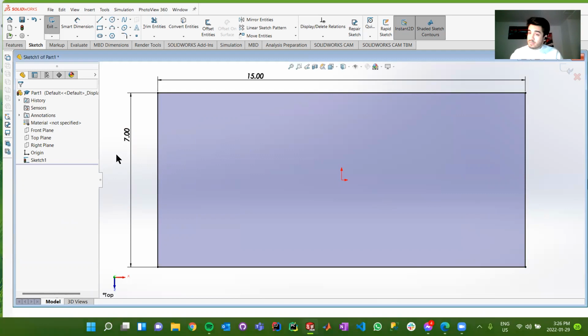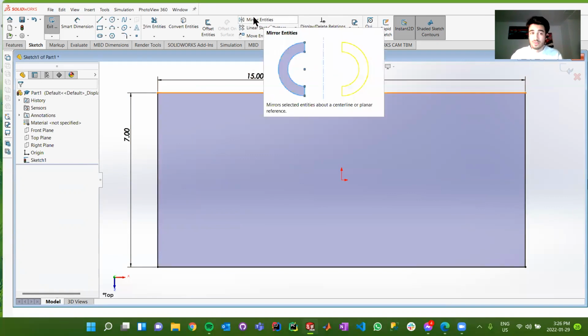Now, another little tip that I like to give when I'm CADing is to not repeat repetitive work. In this case, we want our chassis to be symmetric, at least for the base. And to ensure symmetry, what we could do is go and CAD arms on all 4 corners of this sketch, but that's wasted time. What you can do is make your life a lot easier using the mirror tool.